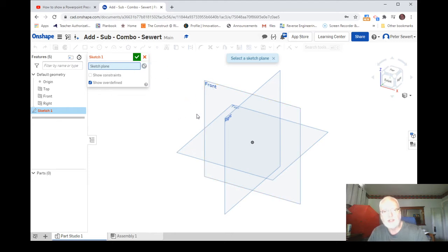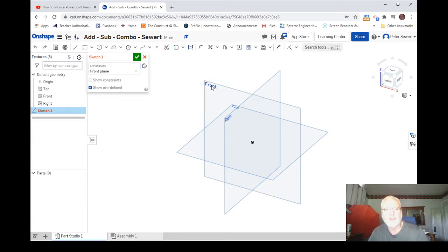And in this instance, you can put it on almost any of these, but generally I like to start with the front view. So I would say for right now, just always use the front view, okay? So I've clicked on that, and you see it added a bigger rectangle there that says sketch 1 in the upper left corner. You'll also notice over here in our model tree that we now have sketch 1.